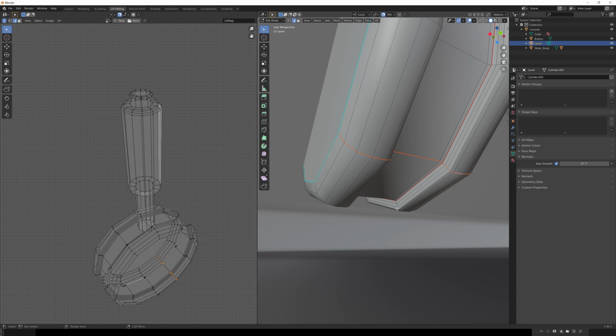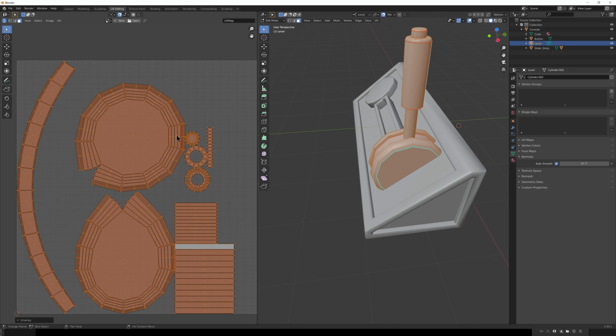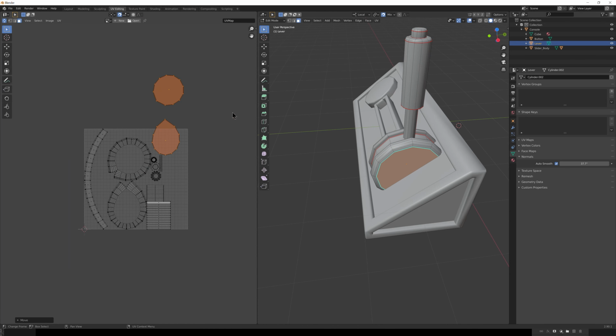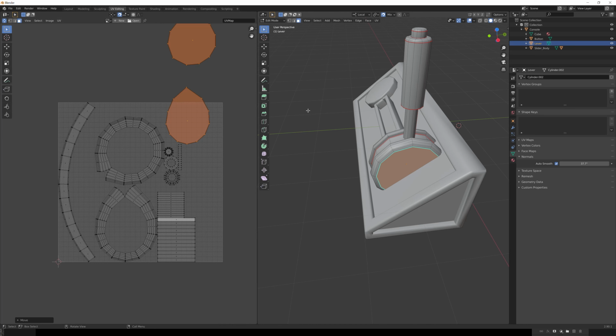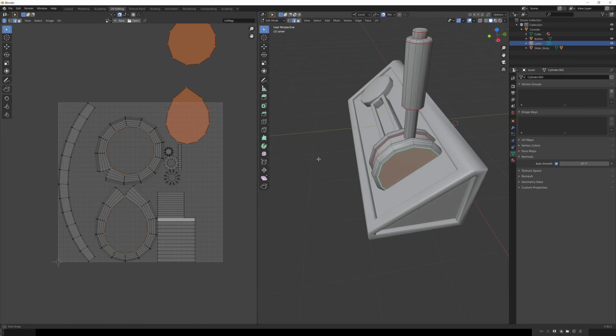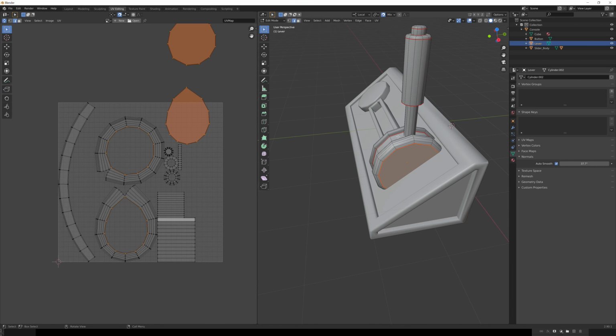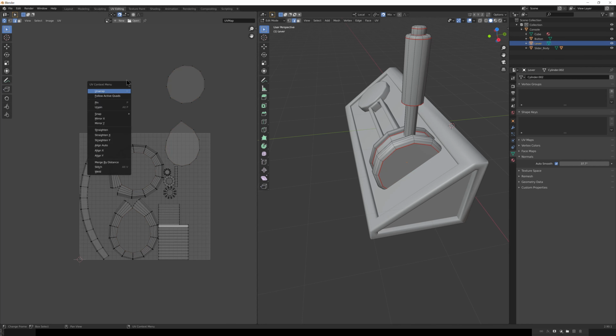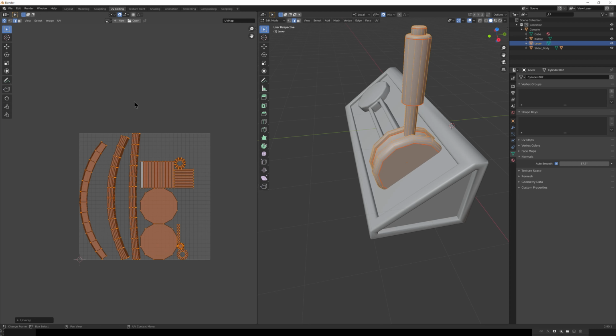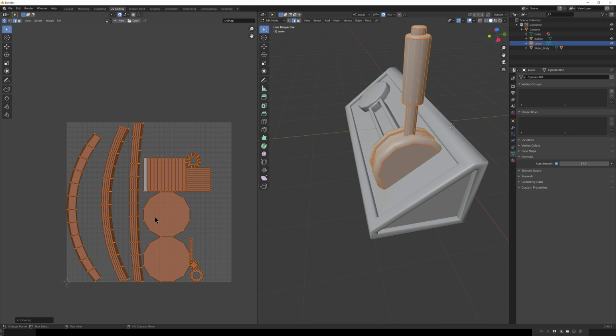So if we select the entire object, I'm gonna hit 3, A, right click, unwrap. As you can see, you can get pretty fast. You'll notice what that seam tried to do right there, but we failed to add seams here and here. So I'm actually gonna hit the G key and move them sort of off. And let's actually right click and let's see, I think we have to be in edge mode, right click, and I'll mark a seam along that as well. And now we can hit A, right click and unwrap, and now you'll see things coming across much better.